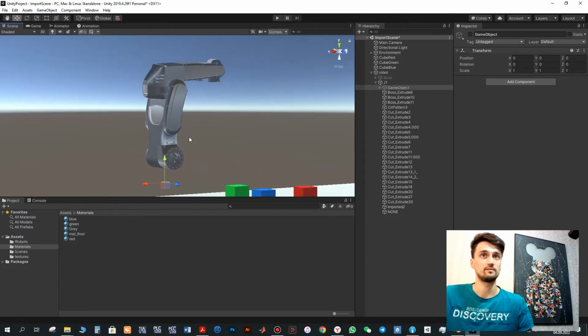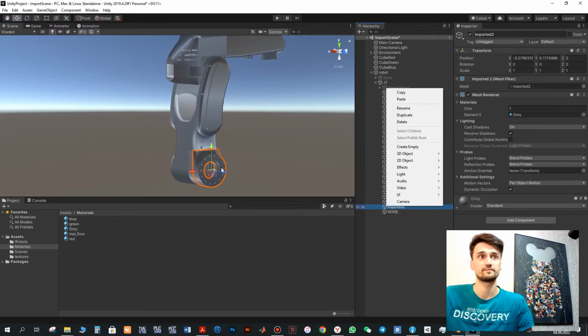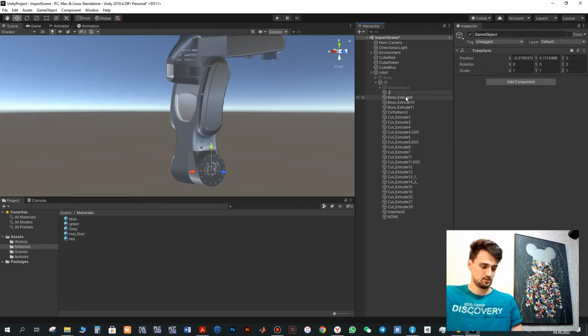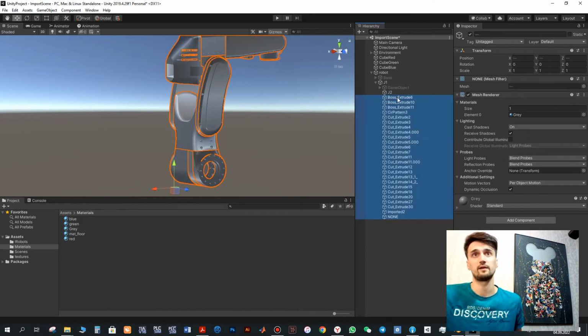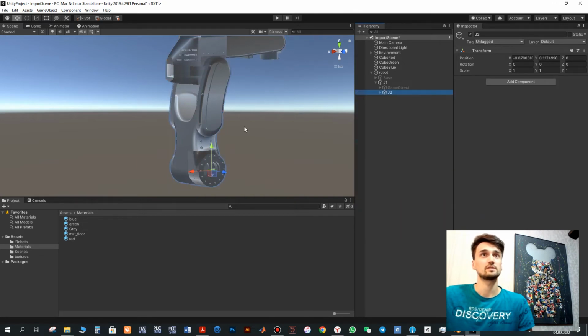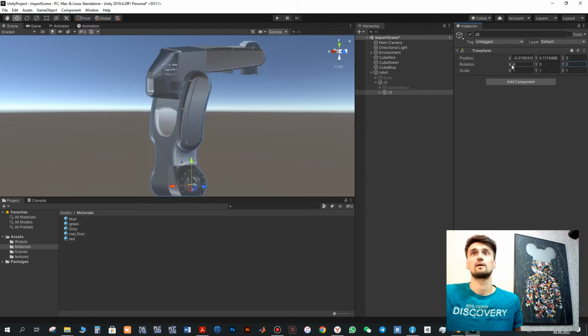So next we will operate with the second joint, and it will be rotated around this region. So again, we need to create a region here. We create empty component, move it up, name it as joint 2, and firstly move everything there. Again, why we moved everything? Because if we rotate here, all of the components above should be rotated as well.